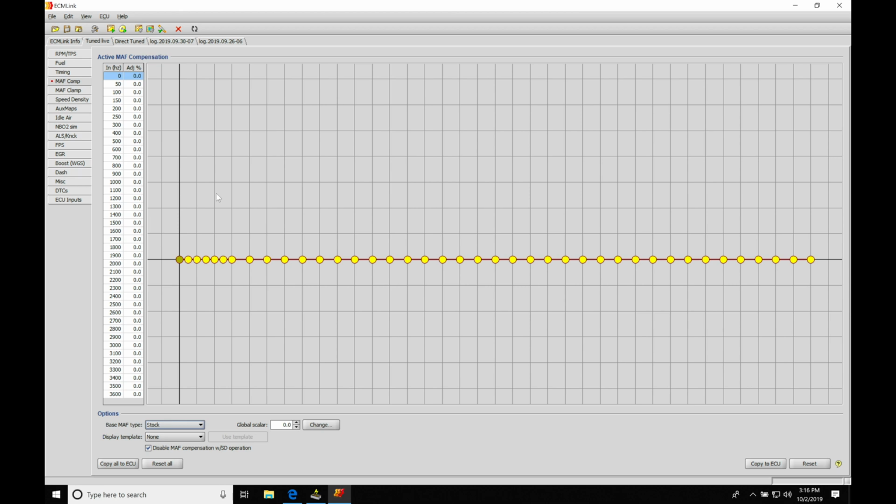But right now, before we go into this, we need to understand how the closed loop operation is going to be functioning in our ECU. So this is going to be playing a role in how we actually go and tune the idle and part throttle areas of operation for the mass airflow sensor curve, and that's going to be a large part, or the large area, of what we have here to work with. So this is going to be important to get our drivability nailed down.